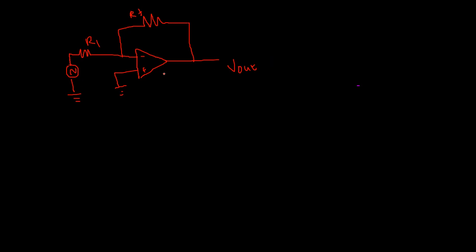In the ideal Opamp, we know that the input resistance Ri is infinity. Before getting into the derivation of a closed loop operational amplifier, we need to know what a virtual short is. Whatever input is given at one terminal will appear at the other terminal. It is not a short circuit, but virtually it is short circuited. So consider this as the Vx node.